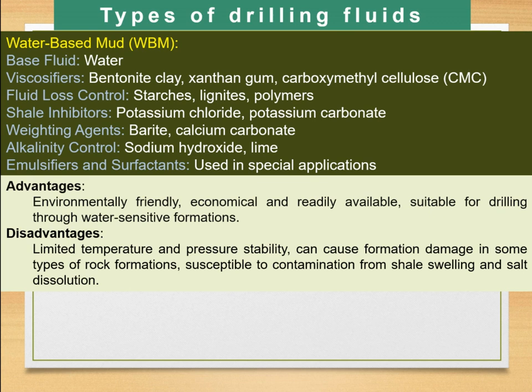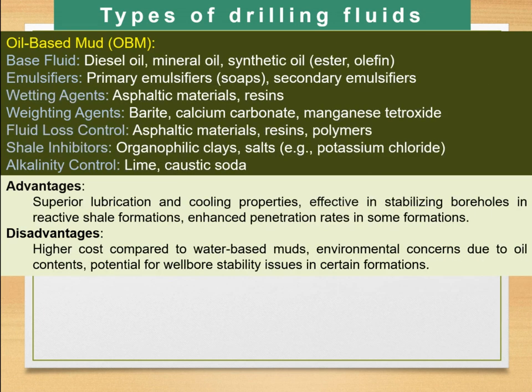Advantages: environmentally friendly, economical, readily available, suitable for drilling through water sensitive formations. And what about the disadvantages? Limited temperature and pressure stability, can cause formation damage in some types of rock formation, susceptible to contamination from shale swelling and salt dissolution. So each fluid has certain advantages and disadvantages. Based on the formation condition, we need to choose.